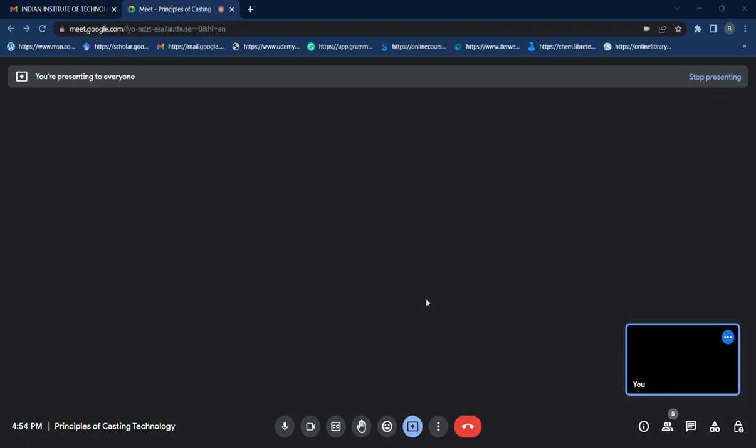So I will write at the end. So if we see the bars case, I have already discussed the definition of bars and plates at the starting of this video. So in case of bars, the riser can feed the maximum distance of 6 root T, where T is the thickness of your bar, to the left part and the right part. Okay, and after the distance of 6 root T, the riser contribution is 0.5 T minus 2T, and your edge contribution is 1.5 T minus 2T.